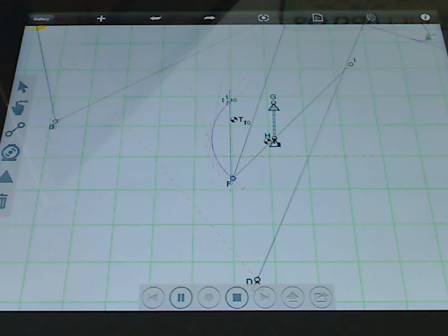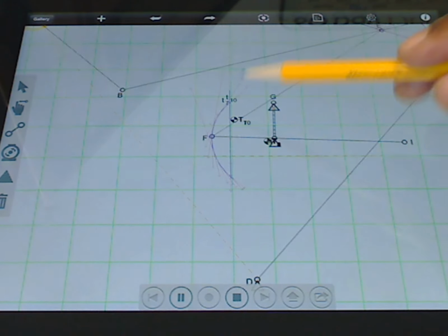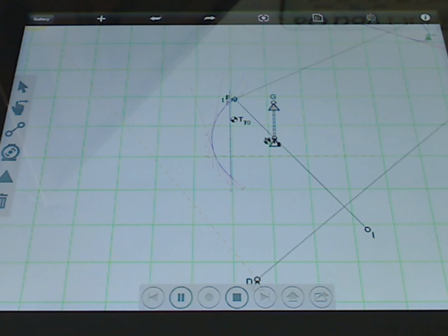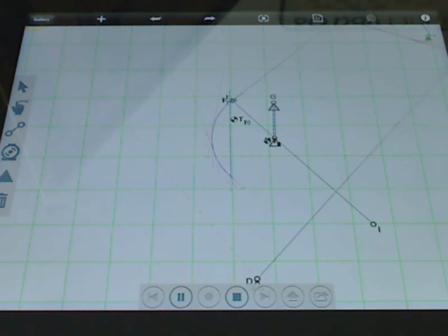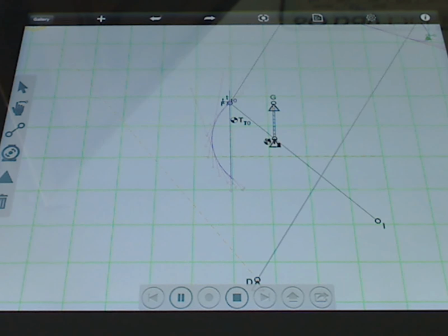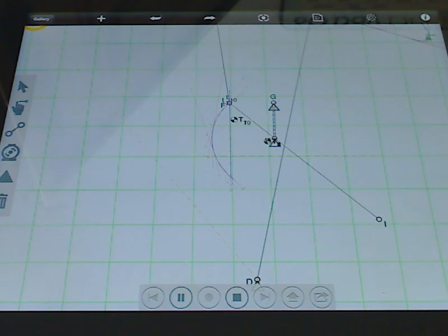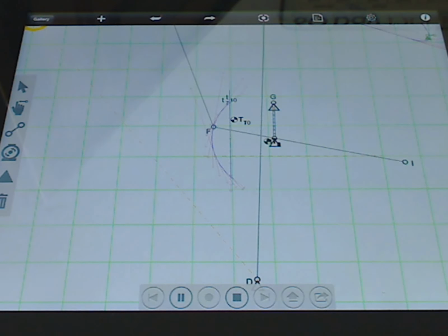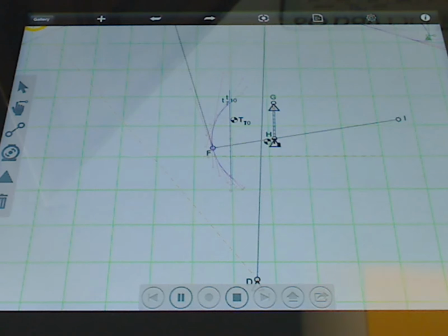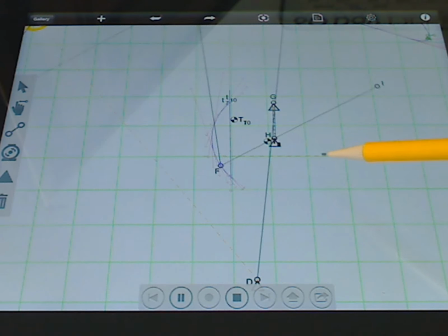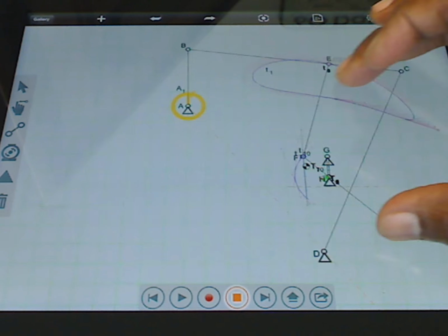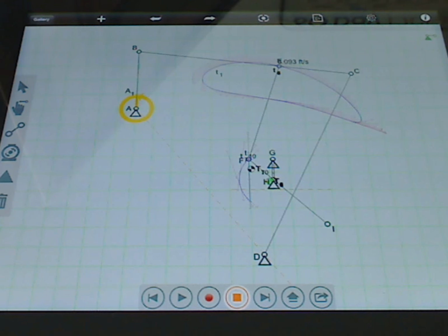We want there to be a 90-degree output from our dwell position up here to our maximum stroke position down here. And so we've got rid of our piston. In a way, the piston was just used to find that maximum stroke length. And then we're going to start moving down again. Moving back down. So 45 degrees we've moved through here, and now we've moved through an additional 45 degrees right about there. And so that shows really how to go about creating a single dwell mechanism.